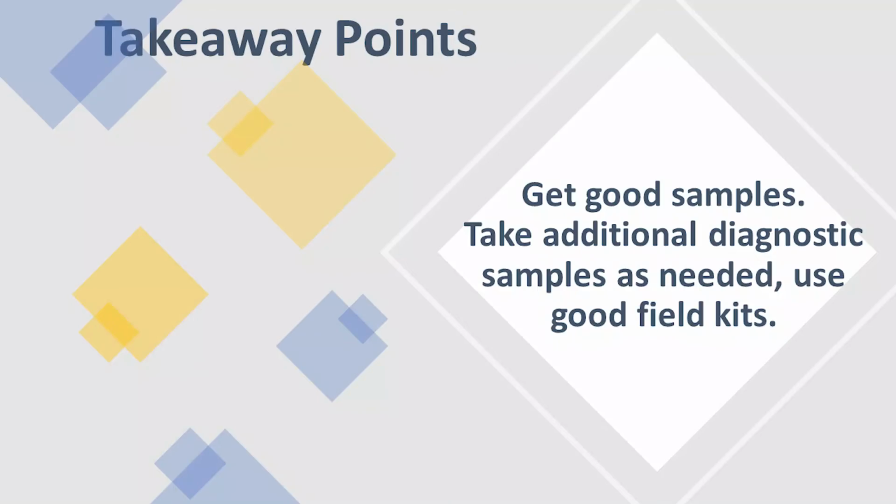And sometimes that means taking samples that aren't quite regulatory samples. And it's hard because that costs money and it's going to cost somebody money. But if you get a good field kit for some of these parameters and actually go that extra mile, measure that alkalinity, find out whether that TKN is ammonia or whether it's organic or not. Those things are all diagnostic.